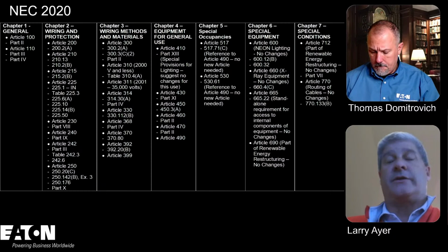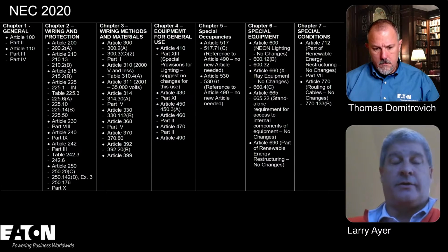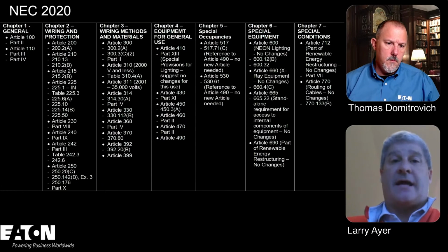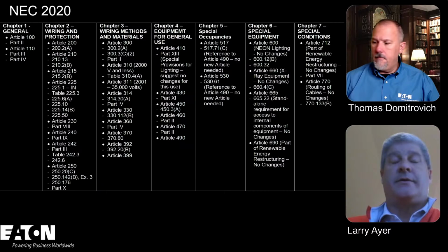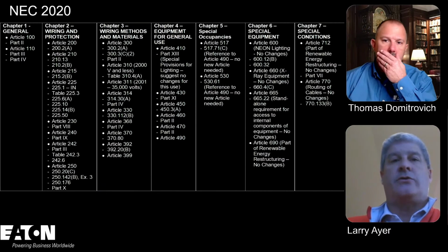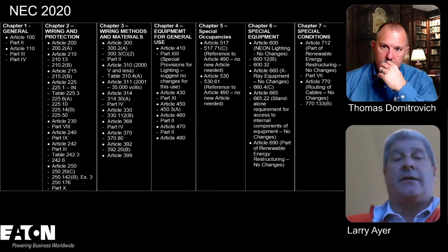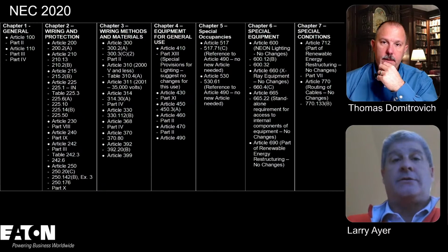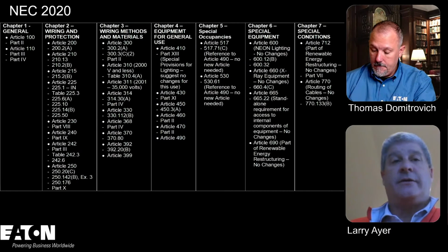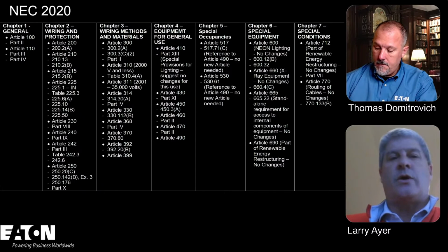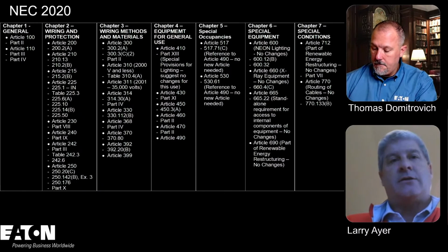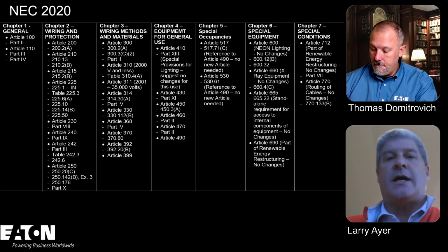The other thing you see a lot of times is that because these code-making panels are geared towards that 1,000 volt and lower concept, they typically take those requirements and mark up conductors 125%. They do that because they think they're always in that 80% breaker world. Right. And so they apply those concepts continuously to feeders and things of that nature, in 215.21 or somewhere around there. They take those concepts and apply them when you don't really have to.